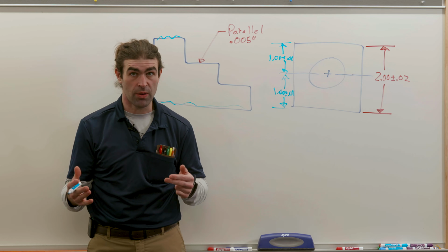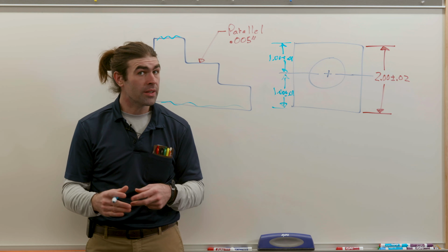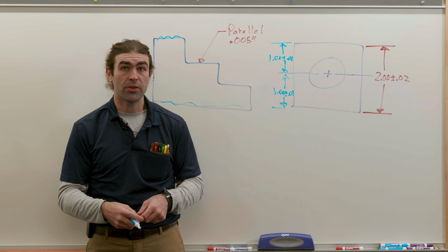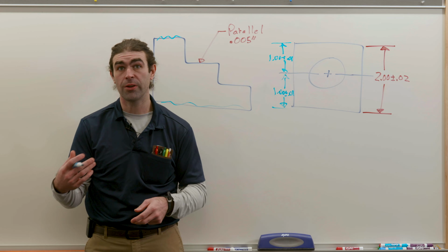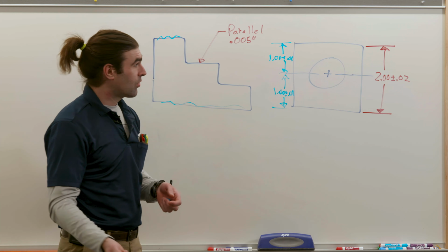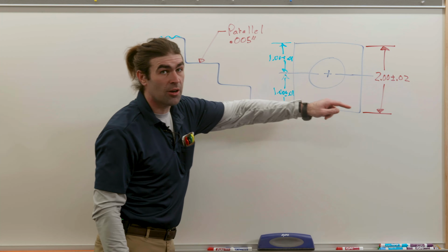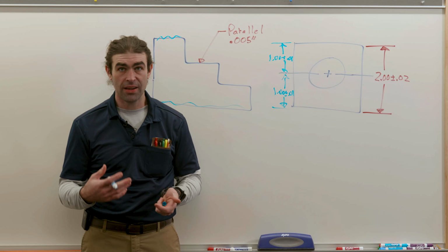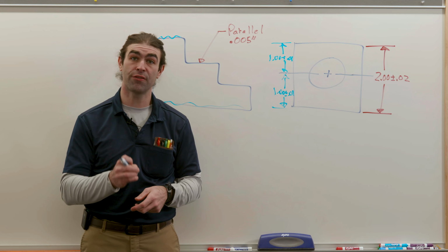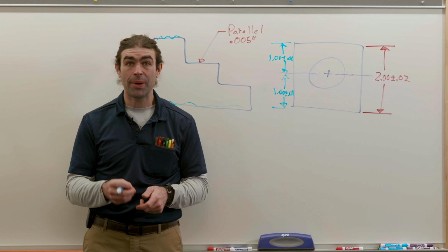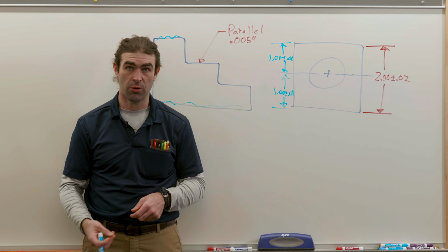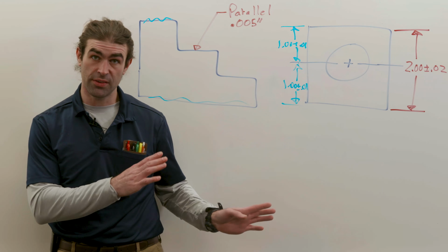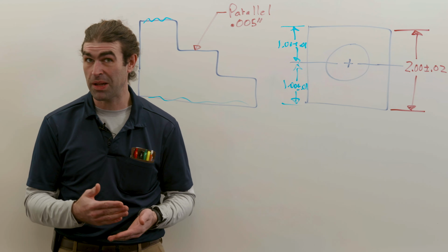Now, none of them are really correct, right? Plus or minus dimensioning really doesn't have rules for how to do this. You're leaving the interpretation up to whoever has the drawing, who's making the part, who's inspecting the part. With datums, we can identify this as a datum and clearly state that the center of this part is a center plane datum, and then the hole is located from the center of the part. It's all about being explicit about the drawing requirements. We'll talk more about datums as we go, but this is good enough for now. Datums are places to measure from.